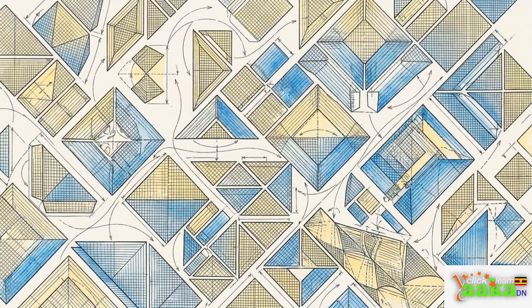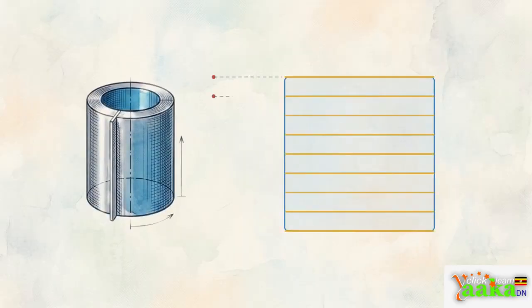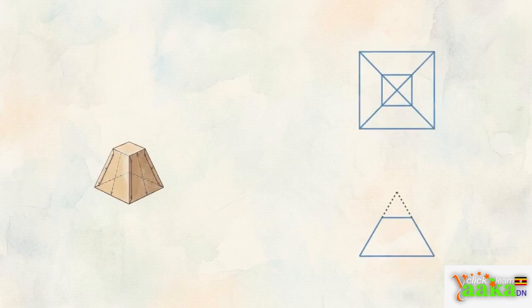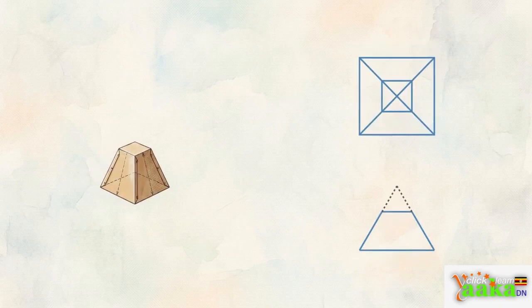Parallel line development ensures precise material efficiency. By projecting lines parallel to a constant axis, the method provides a mathematically accurate one-to-one translation from your 3D design to the flat 2D sheet. Here, we have a 3D model of a truncated pyramid next to its standard orthographic front and top views. Objects like this pyramid, or a tapering cone, all slant toward a single common apex. Because the cross-section shrinks as it rises, parallel projection is no longer sufficient. We must instead use radial line development.